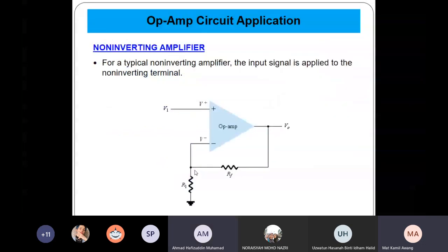If you have inverting amplifier, then you have non-inverting amplifier because you have non-inverting inputs. So for the non-inverting amplifier, you ground the negative terminal and the input to the amplifier is from the positive terminal, just like shown in the diagram.